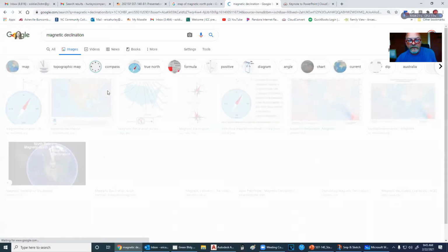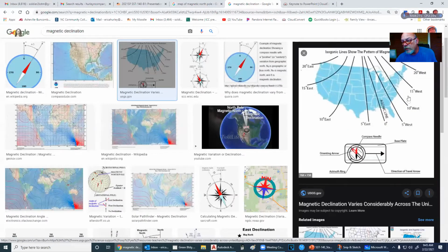And this gives you an idea of the declination. So when we're trying to find solar south, and solar south is down here directly to the bottom, to the South Pole. But if we were up here, then we're going to have to set our compass 20 degrees to the east. But where we're at, we're going to be about 7 degrees. And actually this changes all the time with the magnetic movement of that pole. So you have to go to one of the NOAA sites and find out what the declination is for that particular day.